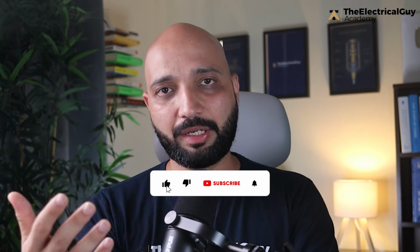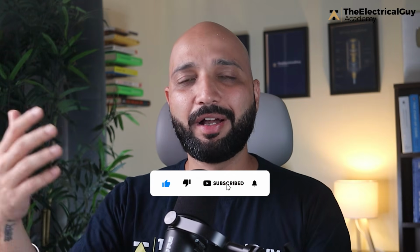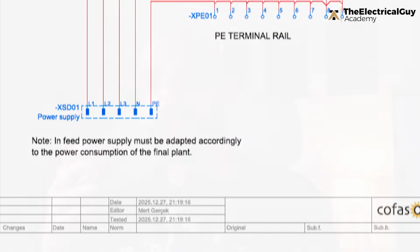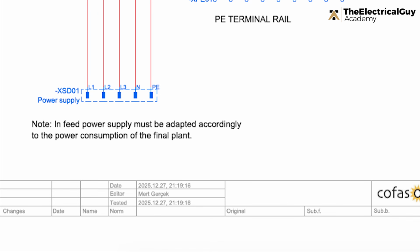For example, in the case of an RMU, one page may show the wiring of the load break switch. The second page may show the wiring of the circuit breaker. So it's divided, and you have to understand the structure of that. The schematics or the wiring diagram can show a regular 3-phase supply in a low voltage application, including neutral and protective earth. So in that case, you have to identify where the power source is.